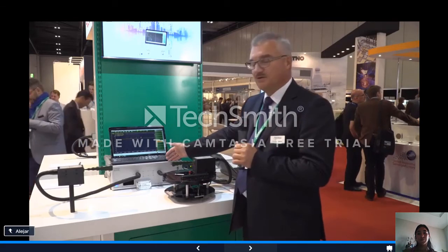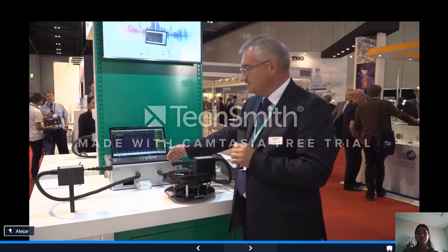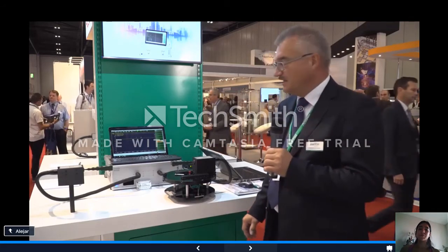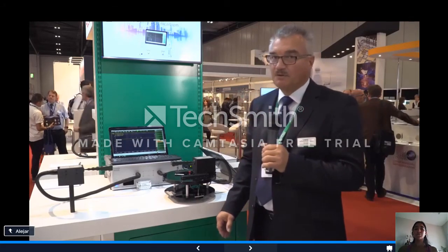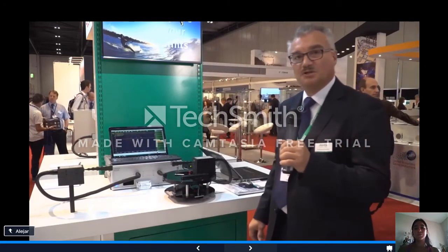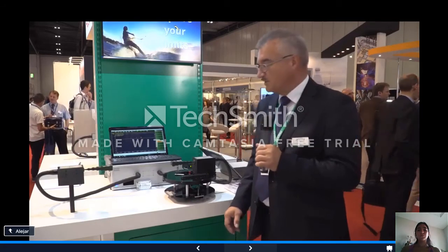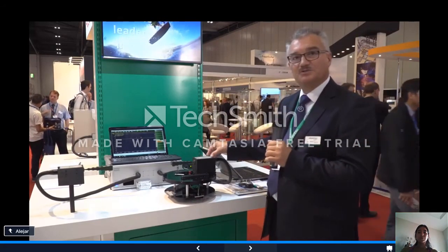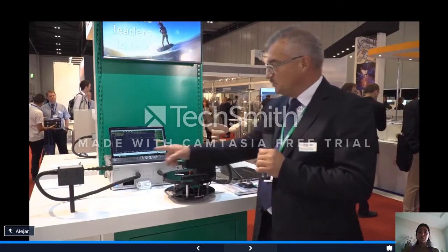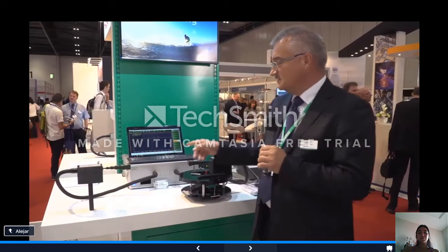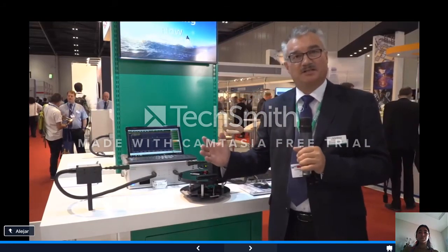To measure an antenna you first have to have a VNA, and this ShockLine Anritsu E-band VNA is a very novel piece of technology. We are using for any kind of frequency conversion the so-called non-linear transmission line principle, and that is the reason why these modules are so tiny and so small. With two of these modules and two antennas, we are able to measure antenna patterns.